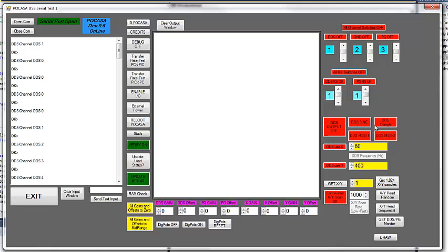Turn your DDS on and off, change your signal from sine wave to a triangle. MSB1 and MSB2 are a divider of the main crystal frequency going into DDS, so /1 would be 24 megahertz, /2 would be 12 megahertz. DDS has 2 registers in there, so you can switch back and forth between the frequencies. Right now I got them set to a preset frequency of 60 hertz and 400 hertz. Switch between them like so. Turn it on, select your frequency.